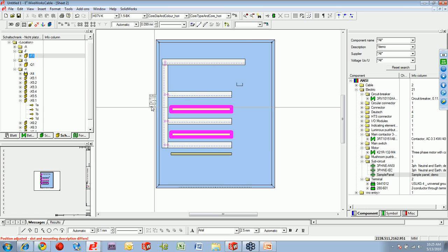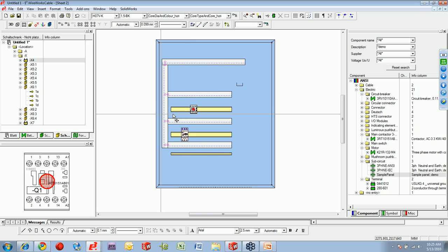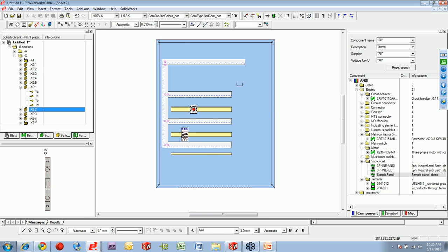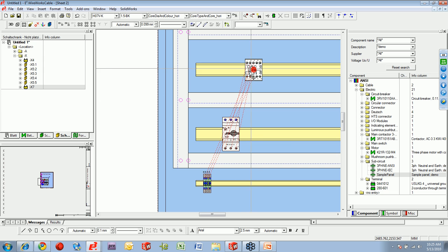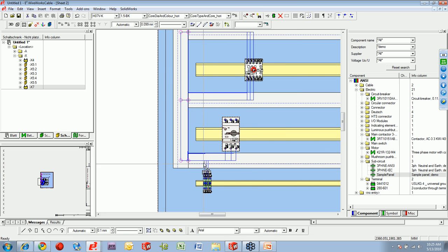Let's go and drop a couple of those in. Just a matter of dropping them and snapping them onto the appropriate rail. So E3.WireWorks keeps track of what rails items fit on. And then, of course, we can take these terminal blocks and drag those on as well. And all of the logic from the schematic that I did before carries over into those red lines. We can actually select all of those at once and auto-connect them, and it will do all of your wiring.